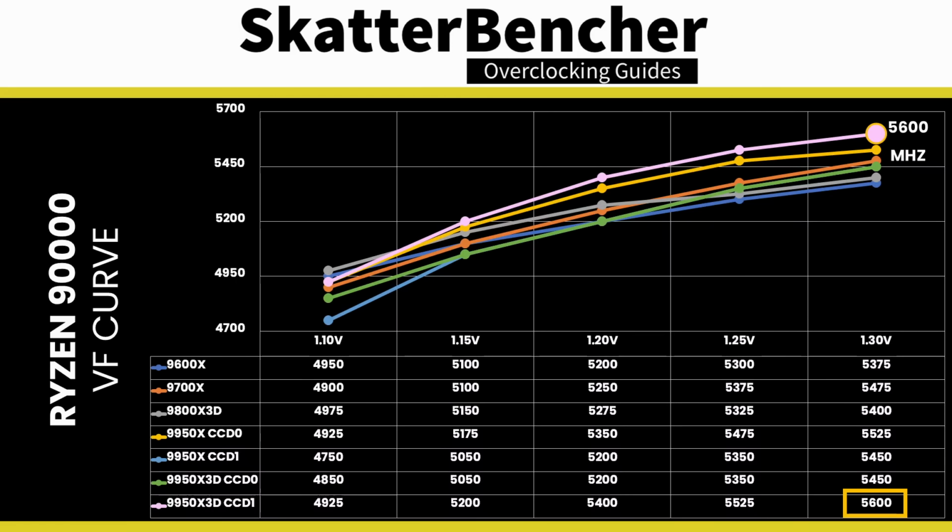The non-Vcache CCD is the best one that I've seen across all of the Ryzen 9000 samples that I've tested. It can run 5.6 GHz with only 1.3 volt when all the cores in that CCD are active. Unfortunately, it doesn't have that much headroom, so I wasn't able to even squeeze it all the way to 5.95 GHz, which would be the Fmax boost override of plus 200.